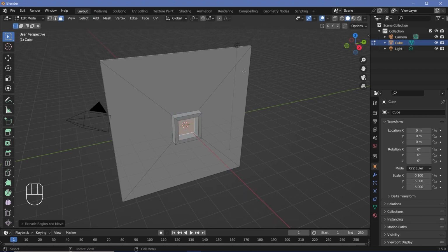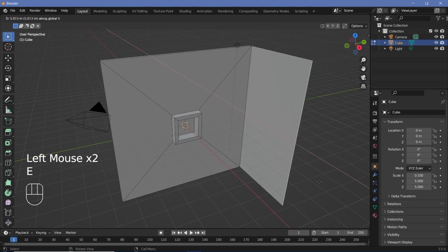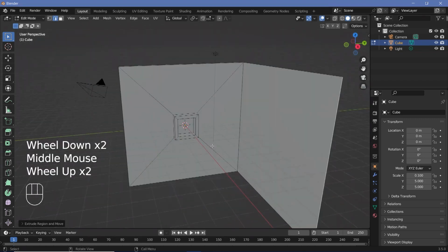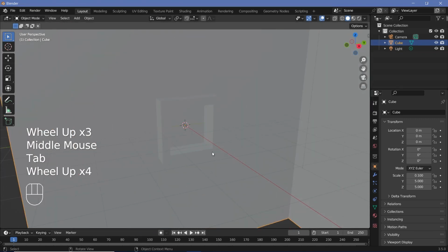Apart from that, we also need this edge to come out to provide some sort of a backdrop when we add in the camera. So we'll go to edge select mode by pressing this button, selecting this edge, pressing E X, and just bringing it out by quite a bit. We'll go with 10 units for now. That's all there is to model the background, but we have to go ahead and add in some modifiers.